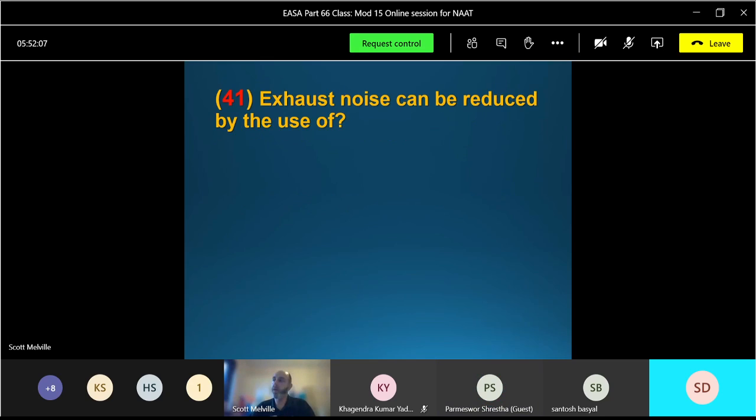Okay, exhaust noise can be reduced by using what? A few different methods. Using low RPM at takeoff. Yeah, we don't need to have the engine at full power all the time. Yeah, low RPM. What else? Insulating, a different type of material on the engine. Yeah, good. And suppressed outlet. Oh yeah, injecting in, yeah. That's not bad. It's close enough. Insulating, yes, blankets.